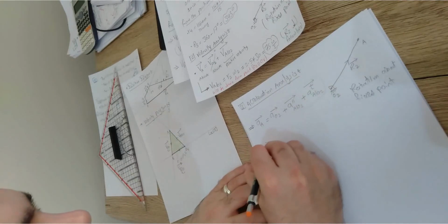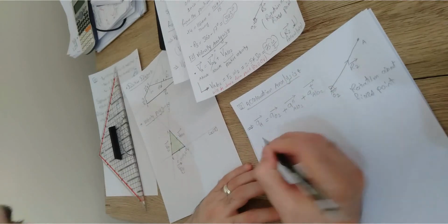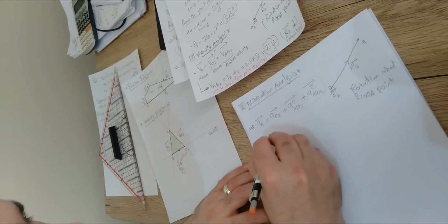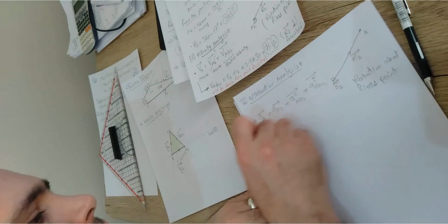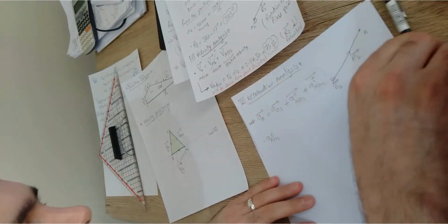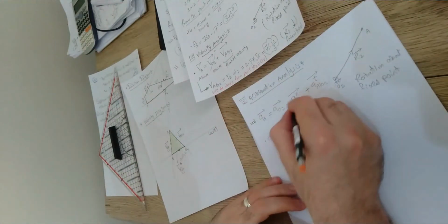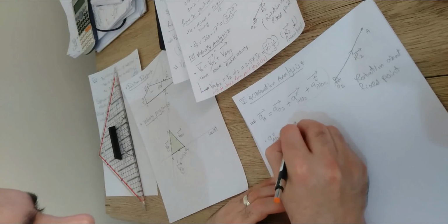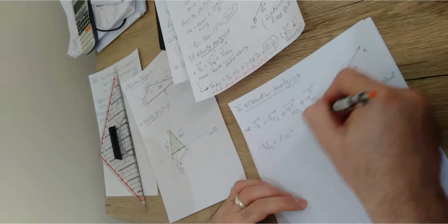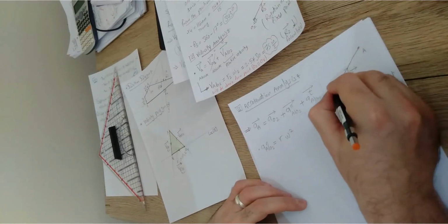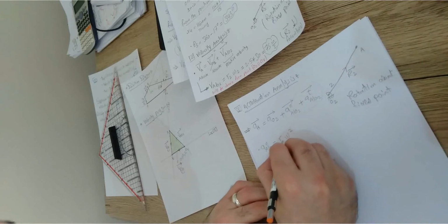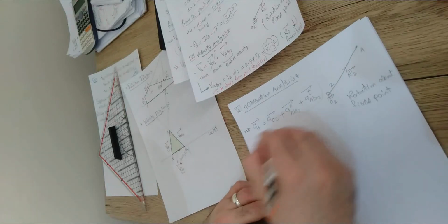We knew from the dynamics class, or even from the complex algebraic method, that the magnitude of the normal component should be R times omega squared. Since we are talking about element 2, it should be R2 times omega 2 squared. What is omega 2?